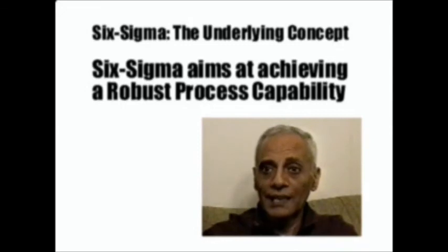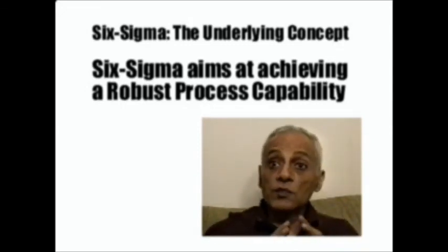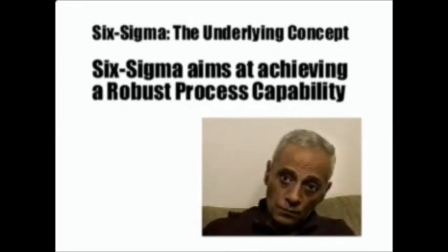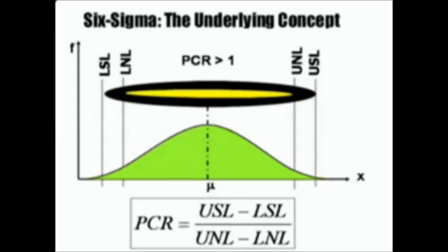But analytically, it's the same analysis. In the past, process capability was viewed as meeting customer specs, meaning our control or inherent or natural limits fall within the customer spec limits. And the focus of process capability analysis, if you recall, was always upper spec, lower spec, or sigma of the process. So it was the variability, or really the stretch or the compression or expansion of the normal curve.